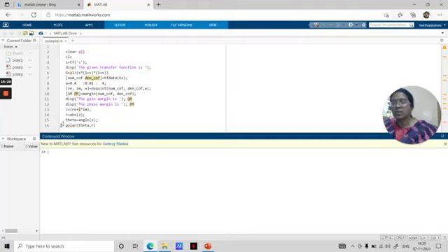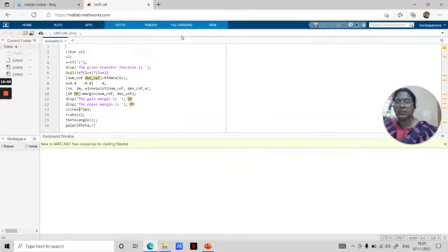Now see here in the command window, first the given transfer function is displayed. The gain margin is calculated as 2 and the phase margin is calculated as 21.387. So the same gain margin and phase margin we got using our calculation that I already explained in the PPT. Now this is the polar plot. The same plot we got in the earlier PPT also, we got the same polar plot. So in this way we can write a code and plot a polar plot using MATLAB.